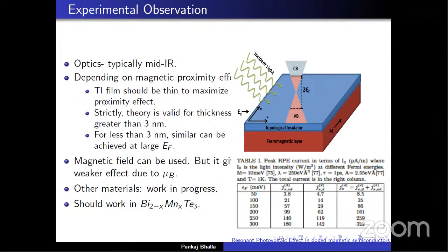So to avoid that, we have put a limit on the thickness of 3 nanometers. Then one can ask why I put only 3 nanometers, not 5 nanometers or 10 nanometers. This is based on the papers or articles in the literature, based on the density matrix theory, where our group has done work on the screening or the Friedel oscillation stuff.